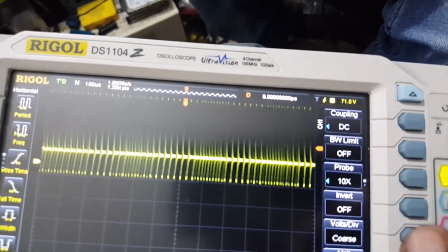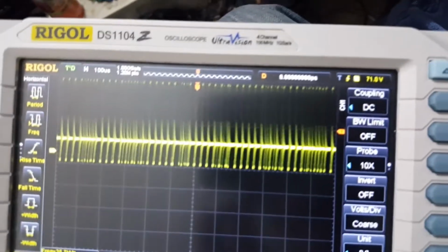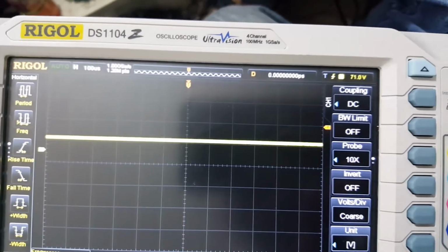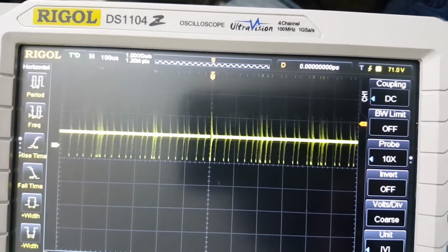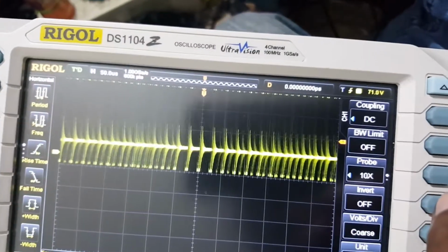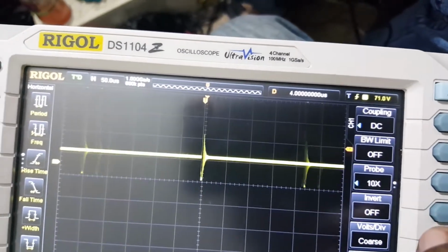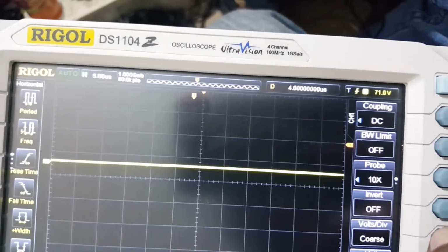Now, this is PWM in full duty cycle, 100% duty cycle. Now we have more noise generated. Check the next side. Smooth. So the filter capacitor is working. If you check the next side, this is PWM in its best action, and the gate is also the same. And this is how switching works: switching on and off, on and off, in a cycle. So that's it for the 5 volt and 3.3 volt regulator.